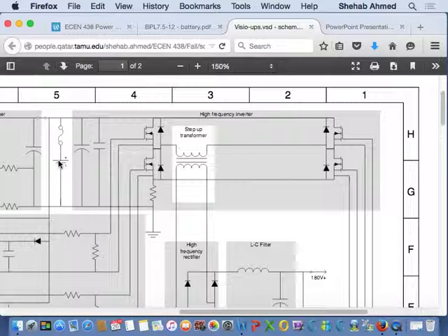So there are many, many types of step-up power converters that we will look at. The simplest ones cannot be used in an application like this, mainly because the simple boost converter that we will talk about later, for example, has a step-up ratio of about maximum practically 4 or 4.5 maximum. So practically I cannot do that. So if I take 12 multiplied by 4, that's 48, right? I'm not at my 120 volts, or I'm not at my 240 volts, right? So I have to find another alternative.